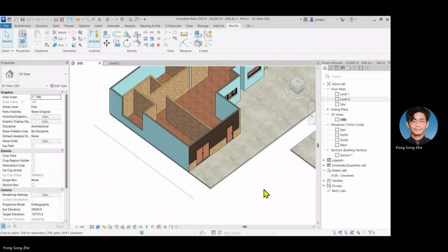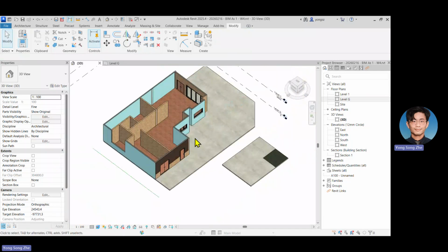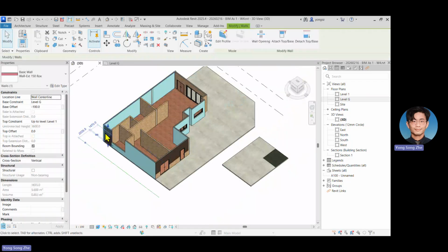Okay, so means in Revit, actually you have a few ways to apply material, more than one way. So the proper way is using the, just now, add this structure, and then you add the finish layer here. This is the proper method. Then the proper method maybe will be used in your company.